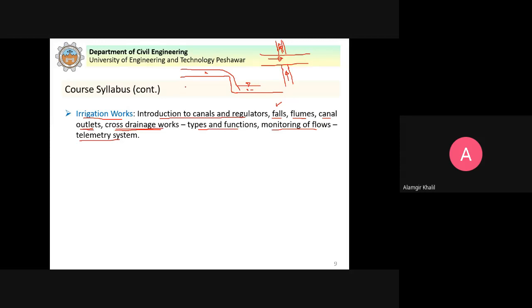Once you measure the discharge, we can develop what is known as the rating curve, which is the depth versus discharge relationship. In a telemetry system, if we can measure the depth of water at that gauge station, then using the rating curve we can estimate the discharge, because measuring the discharge at different points all the time is very difficult.